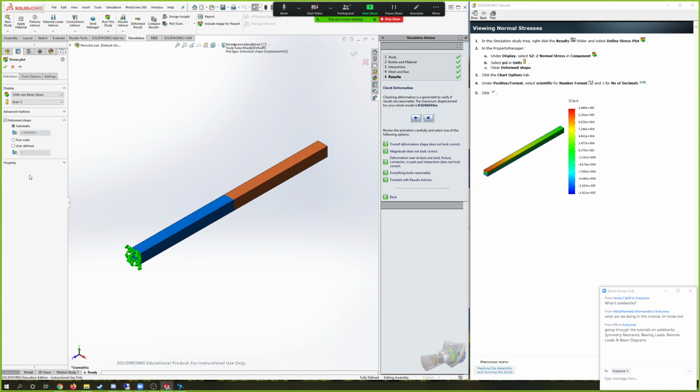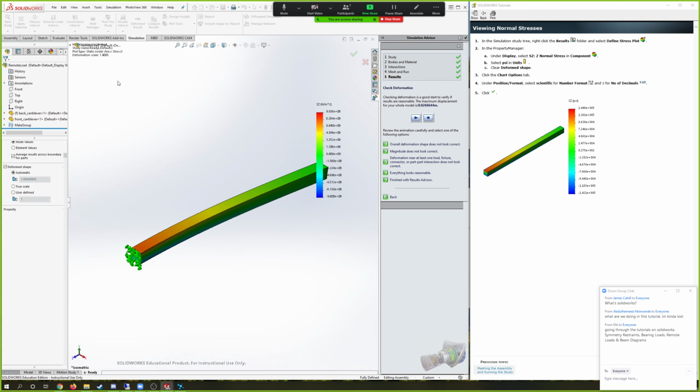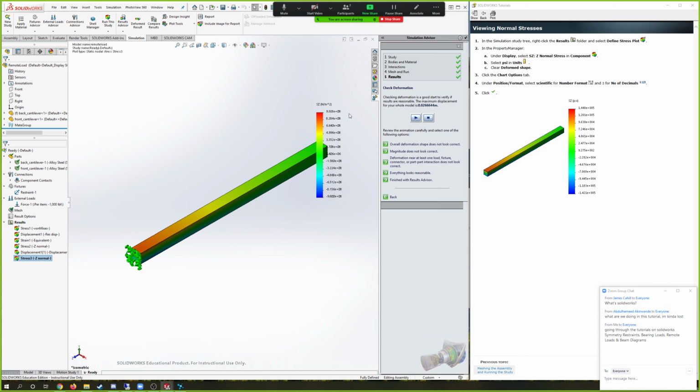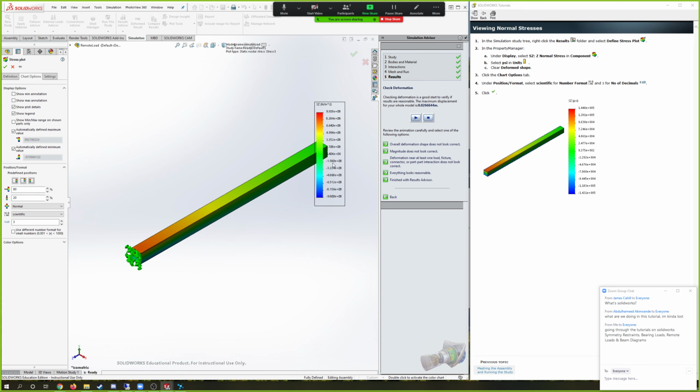Yeah. So I could have realistically just pressed the button. It says excessive displacements are calculated with model. I didn't actually fix it anywhere. Just press OK. I'm getting "excessive displacements were calculated in this model, if your system is properly restrained," blah blah blah. So you've either put too much force or you haven't restrained it properly.